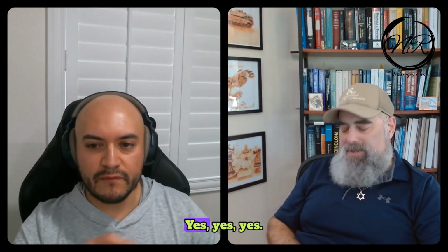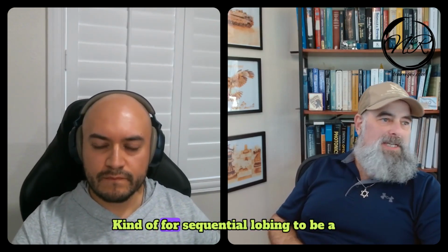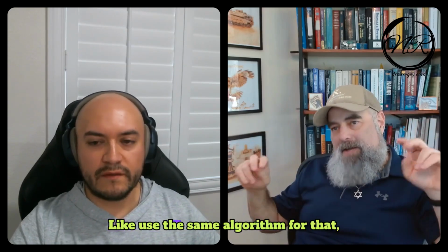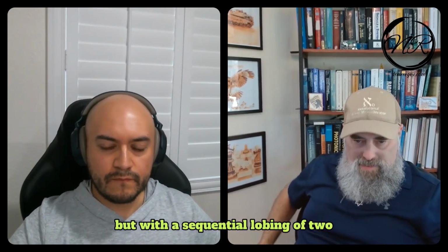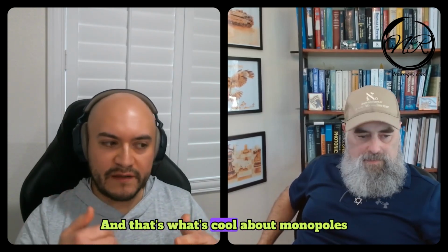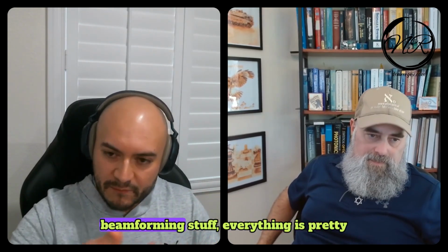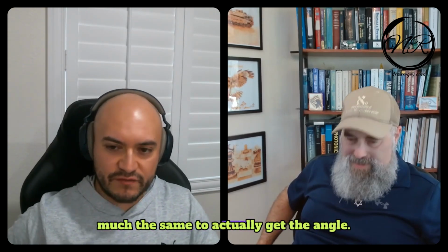You're referring more to sequential lobing, where you kind of force sequential lobing of two to be a monopulse, using the same algorithm. That's what's cool about monopulse: once you get past the antenna beam forming, everything is pretty much the same to get the angle.